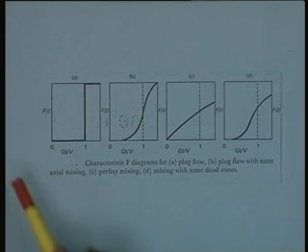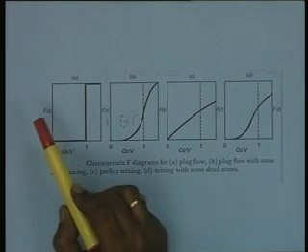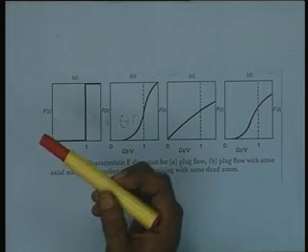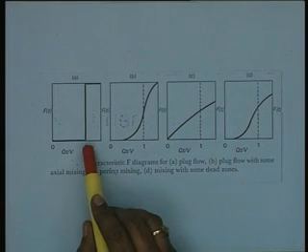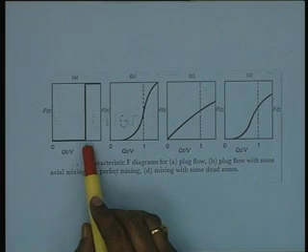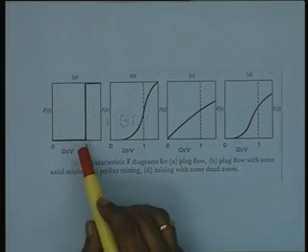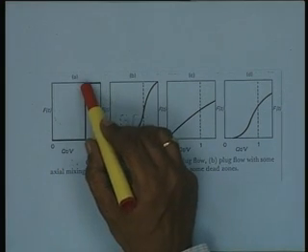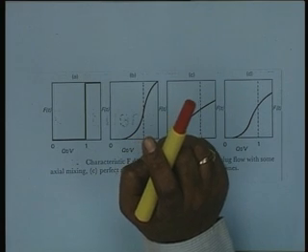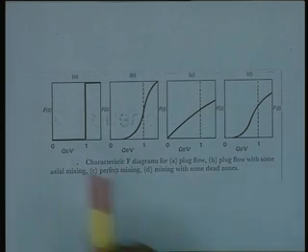That means as soon as the tracer concentration has been inserted into the plug flow reactor, after time t, or Q t over V, that is one residence time, the tracer must come out at the same concentration in the case of a step input.